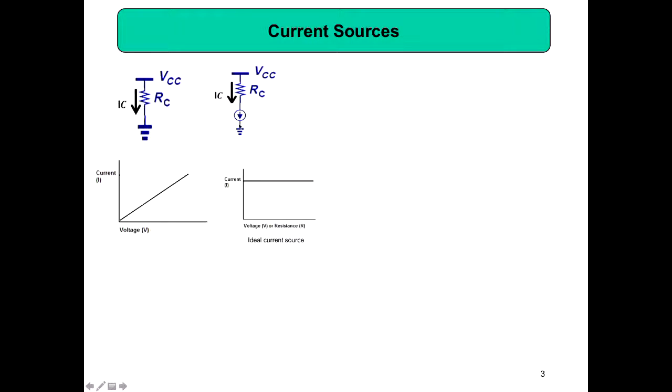So that is an application of a current source. Current source is used in different applications. As I mentioned, when you have a laser diode, you can use a current source. In the CMOS chip, current source is used for biasing. We will come to that point, biasing, because we have seen the load resistance we replace with transistors, and some of them are current sources.